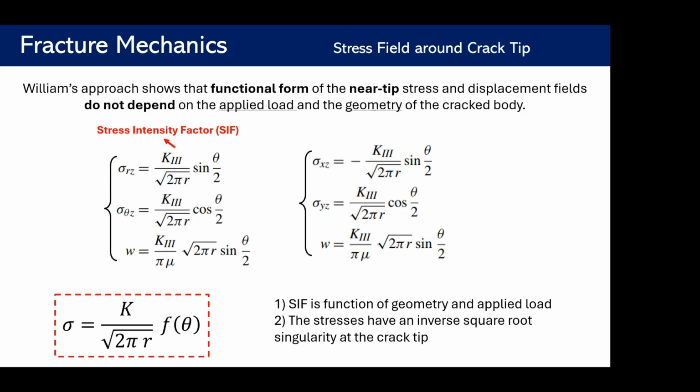And also, we always have 1 over the square root of r, which means that the stress goes toward infinity. When r is 0, we are at the crack tip, and the stress is infinite.